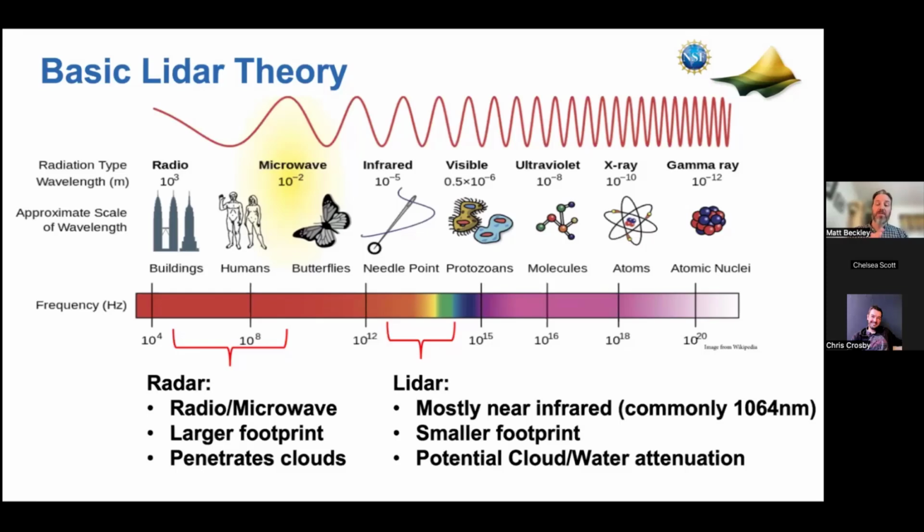The downside to these radars for altimeters and for measuring topography is that because you have this very long wavelength, that translates to a very large footprint on the ground. And so it's very difficult to discern very fine resolution features because you're averaging all the elevations that fall on that footprint. If you want to measure finer scale, high resolution features, that was the motivation to move towards LiDAR, to get a more discrete footprint, and so you can get higher res imaging of the surface.